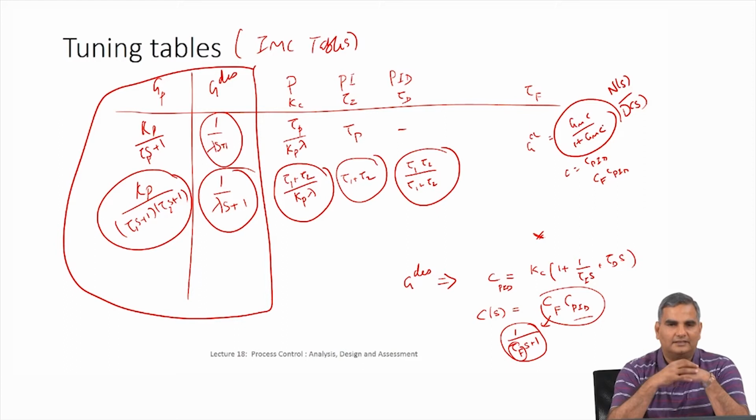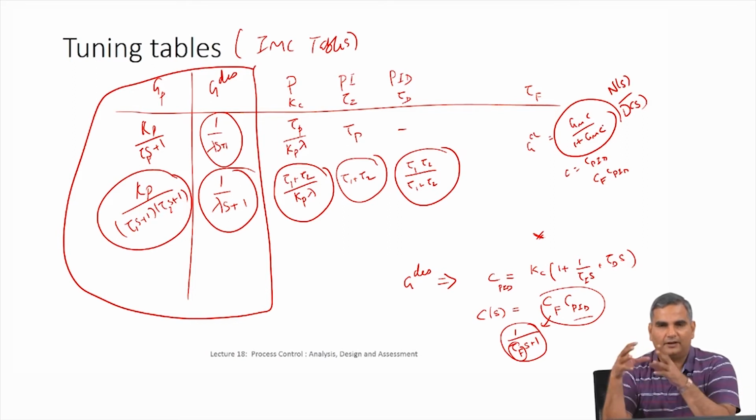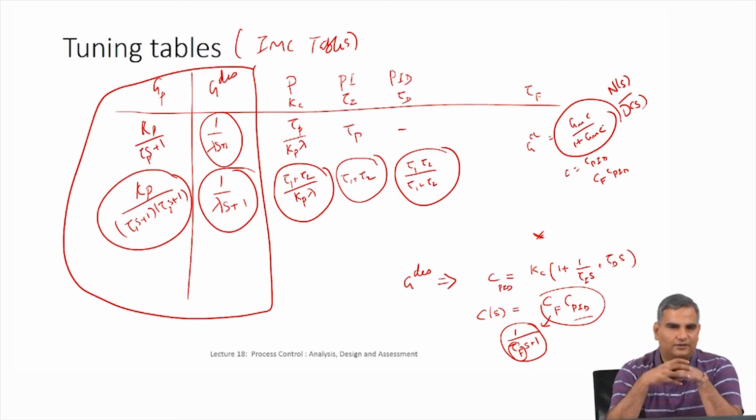The same thing translates to closed loop. You have a y and you have a term corresponding to the set point Y_SP and a term corresponding to the disturbance. Now I said once I show you how to get these transfer functions, then the analysis is straightforward because we are going to use the same N(s) over D(s) form and do whatever we did for open loop systems, the same thing that we are going to do for the closed loop systems.